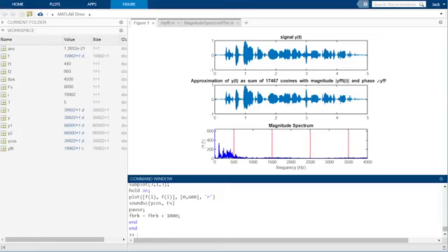But more importantly, we can detect the amount of power in a signal in different frequency bands and display it as the magnitude spectrum for the signal. This is arguably the most fundamental of all signal analysis tasks. And not only can we detect it, we can easily manipulate our signal by picking and choosing the frequencies we want. We can boost the power in some frequencies and diminish it in others, or we can remove all power from specific frequency bands. This is the process called filtering.